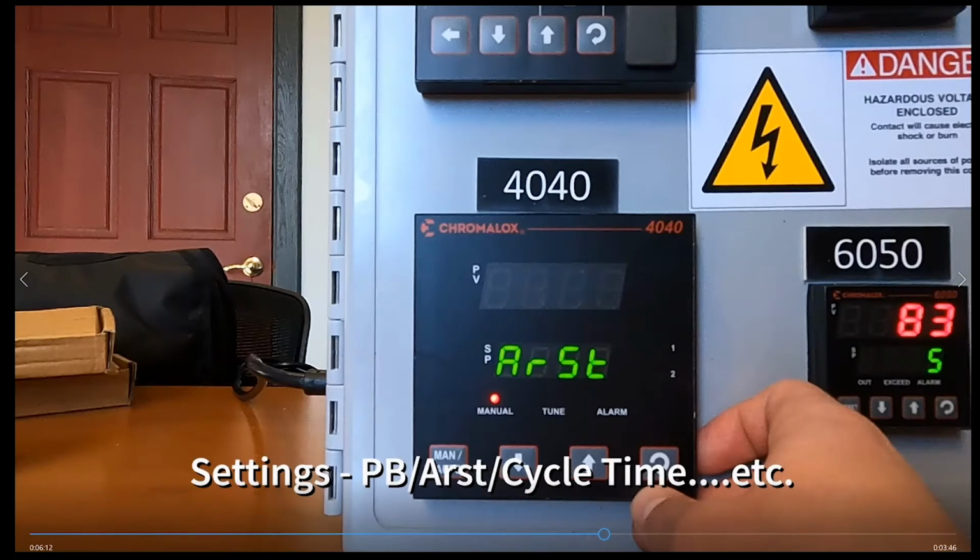It'll slow its reaction, meaning the controller's reaction to activate the heater. If we're talking 1 kW, 2 kW, not a big deal. But if we're on scales of 100, 200 kW, megawatts, this window needs to be a lot larger. I know the default on these things is always very short.